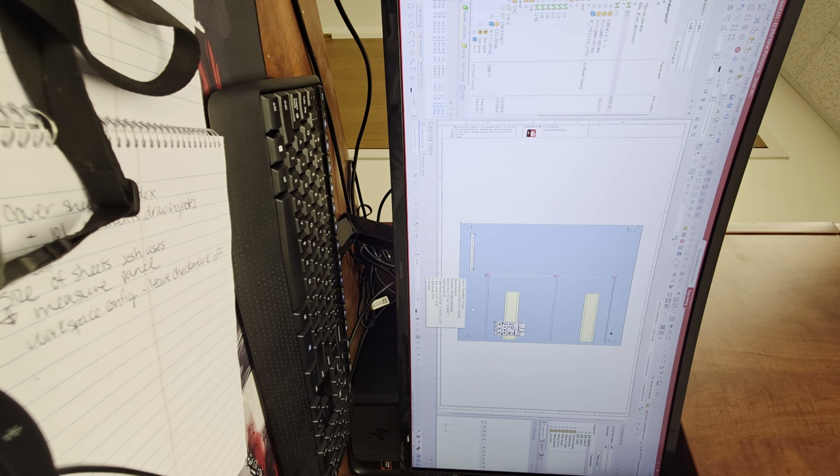Somewhere in the bottom, etc. But the same thing with all these other parts, these paths that you're setting up. Keep in mind if your wires are not showing going from one part to the other, you need the ducts in between. If the VFD and the ground bar are too far apart, the wire will not automatically route between the two. So you will either have to bring the parts closer together, or include the duct in between them, so there's a path for the wires to go and chase each other down.